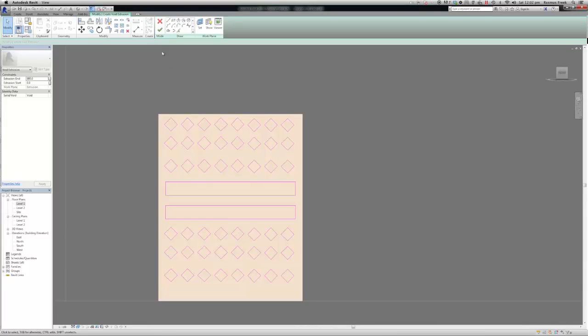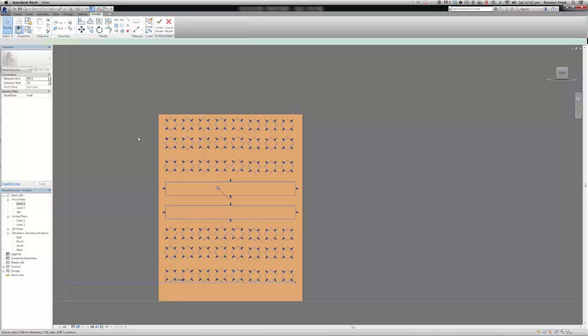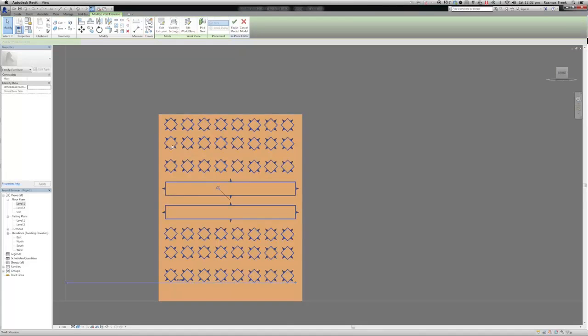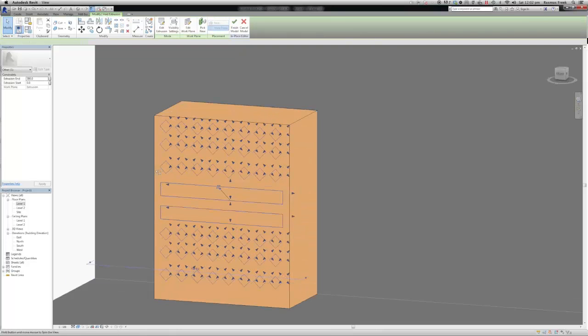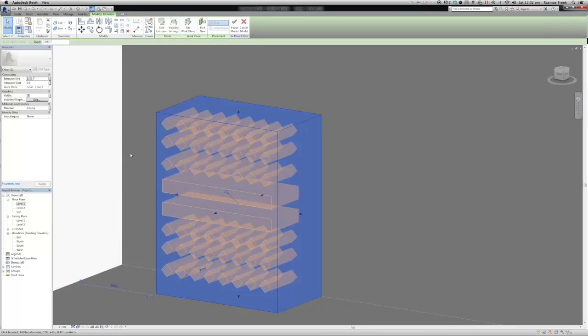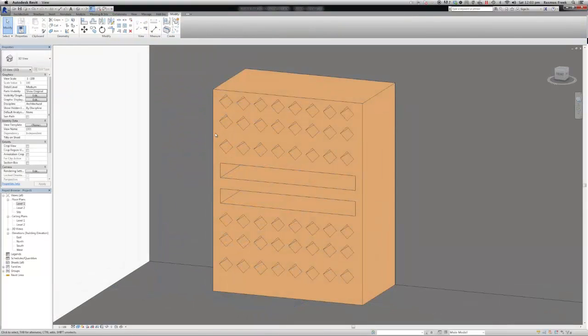When we are finished with the sketch, we can select properties for this void. Let's make the void go all the way through. Finish the model. Now we can see the finished component, which is a combination of both solid and void forms. Exit the InPlace editor.